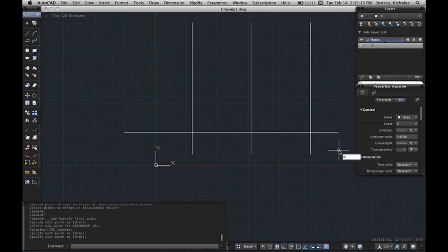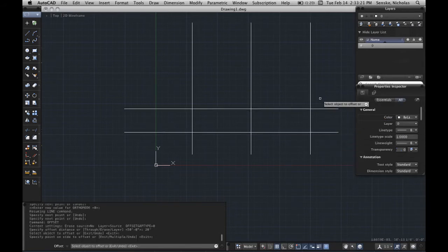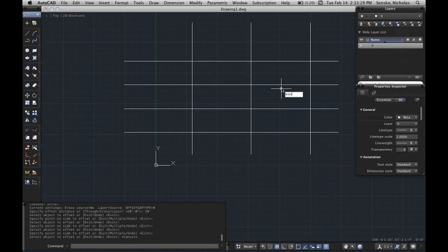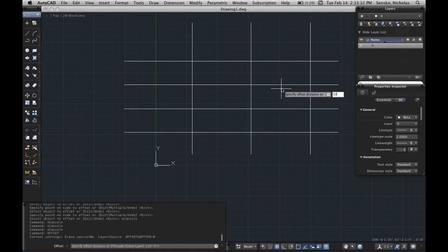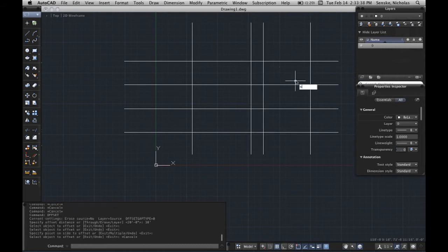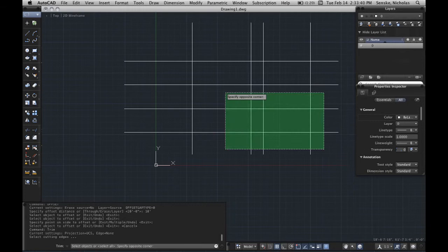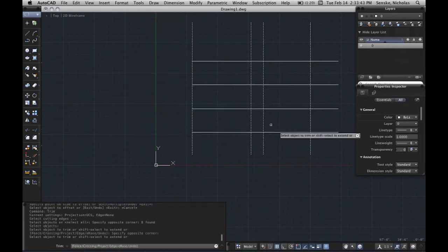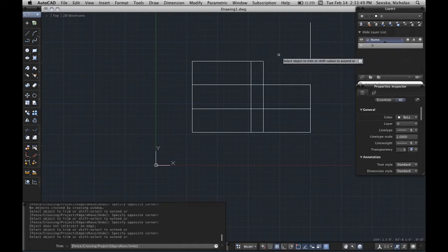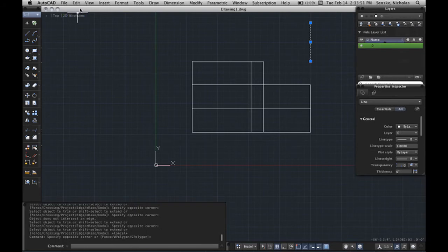And then I say, okay, then I know that this is maybe part of my diagram or some kind of site feature, and that's maybe 20 foot off. And then I could begin to actually draw on top of this with another color, or I could offset these like 10 foot, and I could begin to use trim to clean this up a bit so that it's actually my drawing. And then just keep working it that way.